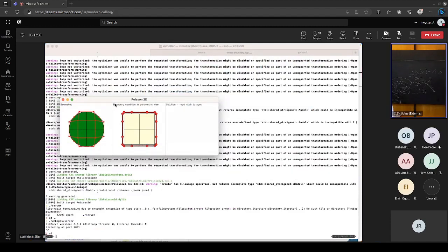This is the tool that TU Vienna has been developing. Another feature, because this was all geometry modeling, but not the right-hand side. What I can also do here is, of course, model the geometry, but I can also modify, let's say, the boundary conditions. Here I have visually modified the boundary conditions. They were all 0. Now I make this one something like 1, and I see that it really changes.